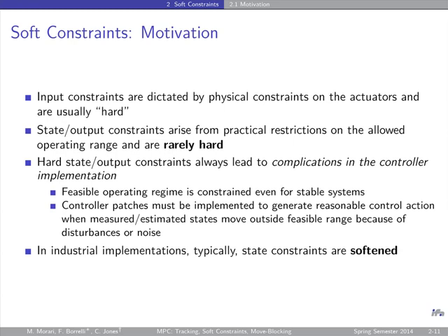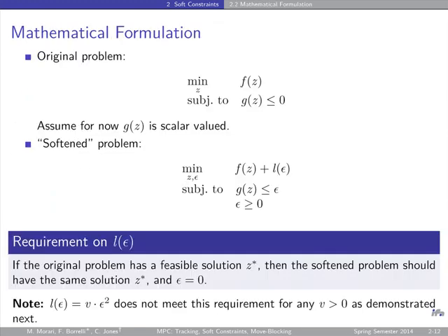On the other hand, there's the other modification that I just mentioned, and that's called move blocking. What move blocking does is, if I look at my t, and at my manipulated variables u, and let's say those are the time intervals, then move blocking says, after time interval 4 here, I don't need to determine the u's so accurately. I will just assume that over, let's say, two steps I have the same u, and then afterwards I can change it, and then from there to the end of the horizon I use the same u. This makes sense because you reduce the degrees of freedom. Instead of having maybe 10 degrees of freedom, you have fewer.